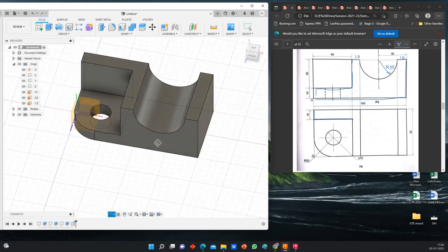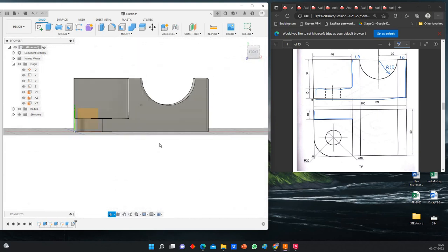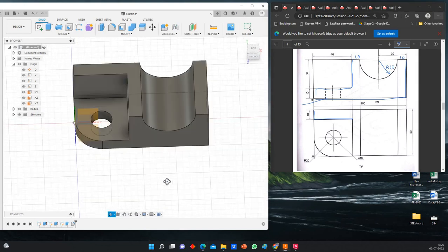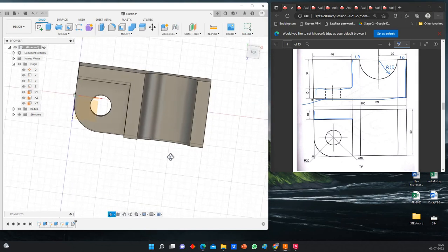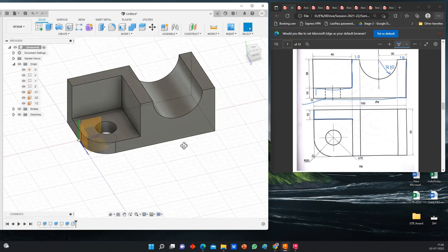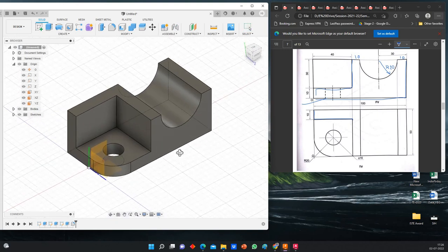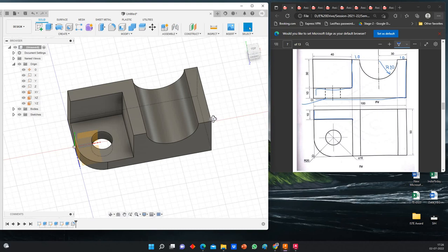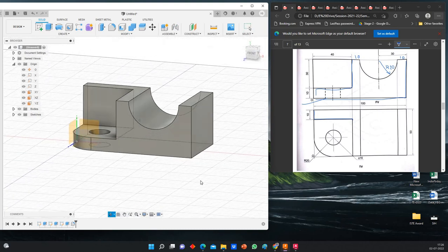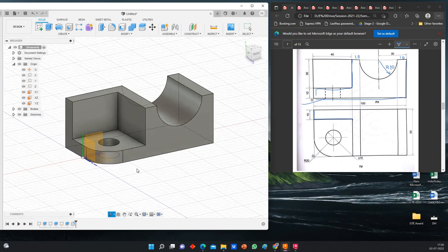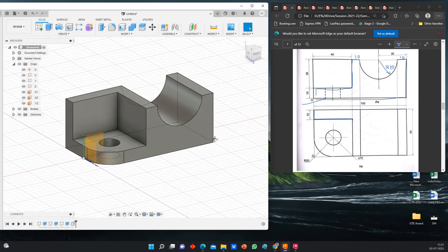Okay, so now see our drawing, the isometric model is now there. So this is the front view. You see this is the front view here. And if you see in the top view, it is something like this. So this is the method to draw the 3D model in Fusion 360. While drawing the semicircle and this circle, we have to use the 4 center method. And all lines must be parallel to the length, width, and the height.